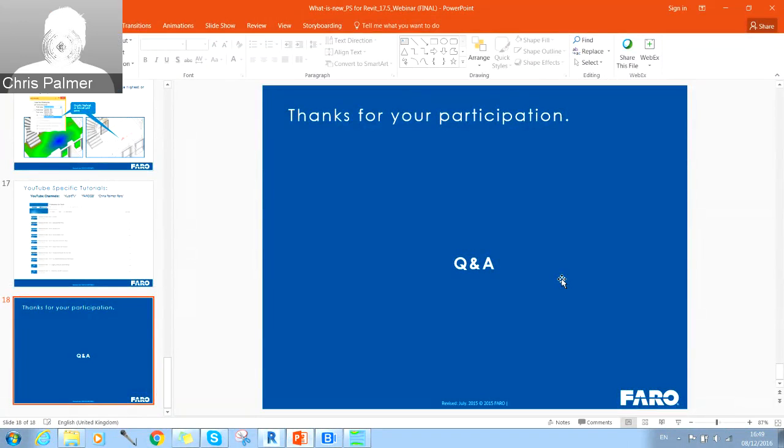Hopefully that was covered during the presentation, but just to recap, obviously we are only working with what's visible. So if we have a pipe that's got insulation on it and we've scanned that, we are working to the outer diameter. So we can specify the insulation radius and the size and things like that, but that's not intuitive, in terms of it can't see through the insulation to the pipe. It is just a case of using your engineering knowledge to determine what that should be. Which is really the case if you were modeling it in any other way as well. There's no real way to test that unless you either know or you manually check it.